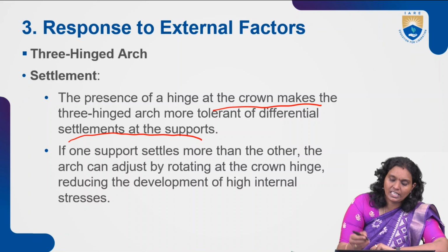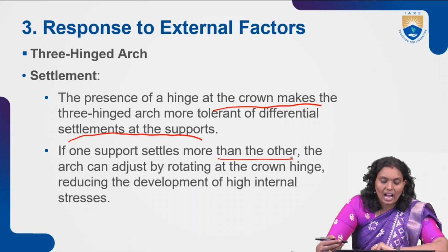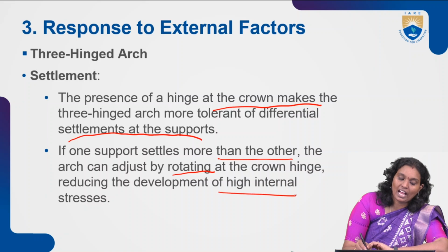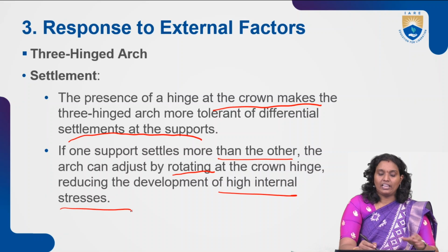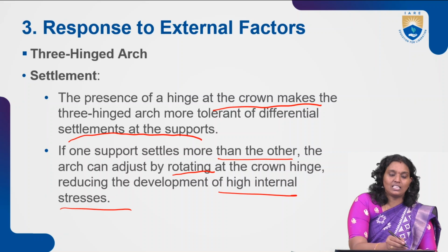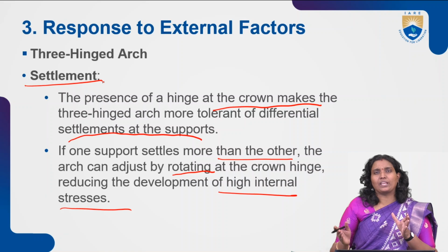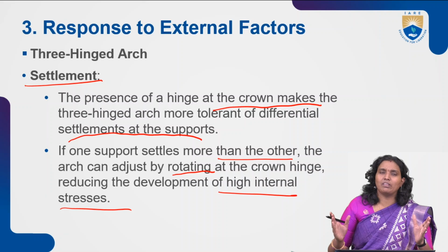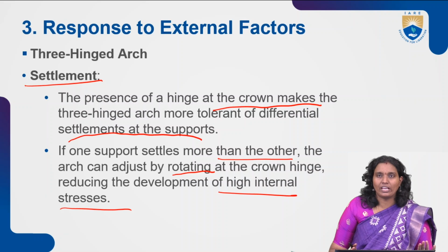If one support settles more than the other, the arch can adjust because of the rotating flexibility at the crown hinge, reducing the development of high internal stresses. Different settlements may occur because of different loading conditions, so throughout the span we may not expect the same kind of loading conditions.